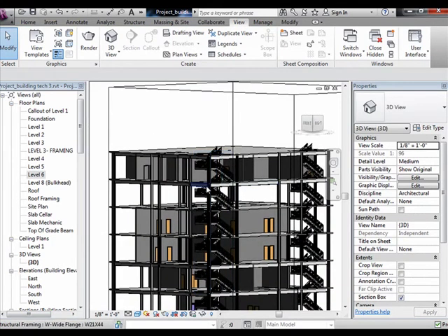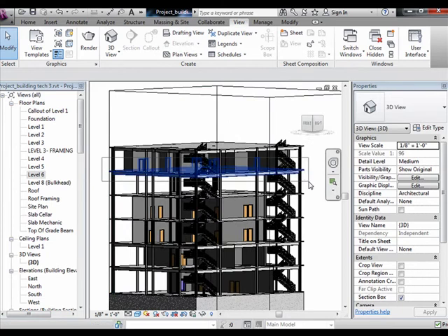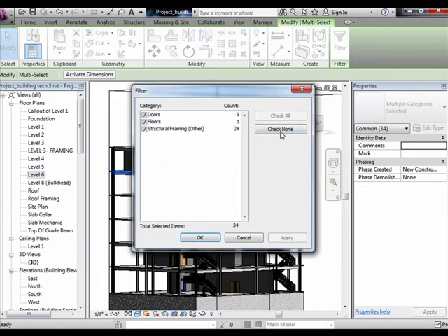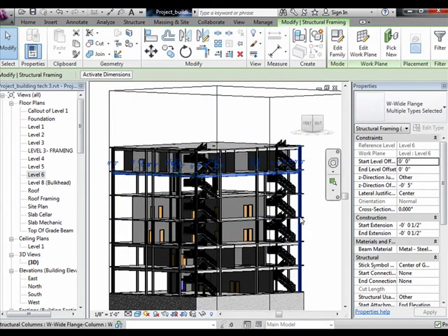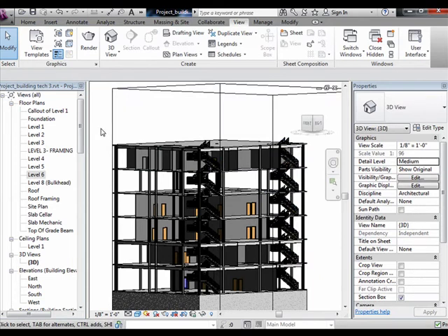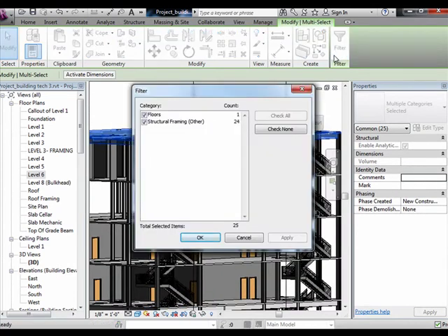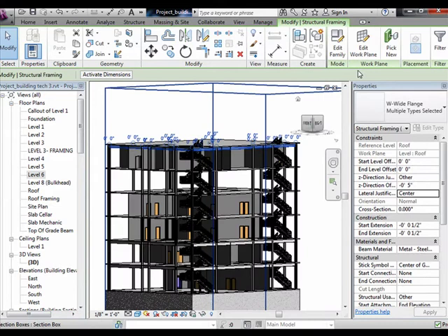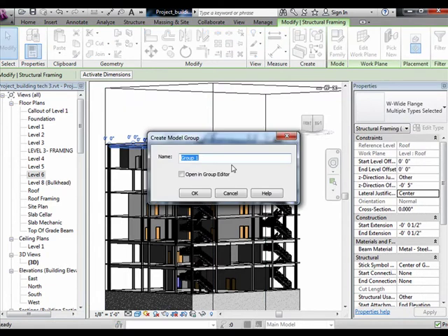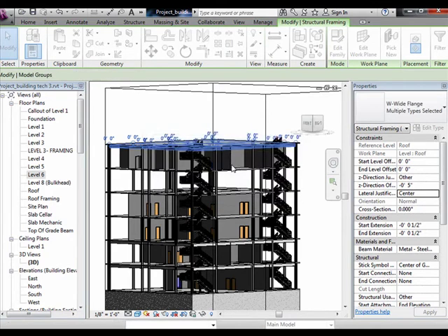When you develop your one level of beams, forget about copying all the beams and selecting them. As a rule of thumb, always group your framing, your similar components. I'm going to select the top floor, those beams here which I've created, they have been created, but I'm using them. Alright, group it, GP shortcut, and name it typical framing, meaning that framing will repeat throughout the whole building, 2nd through 6th. Hit OK.